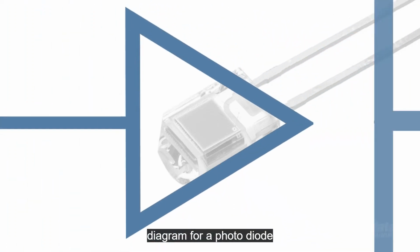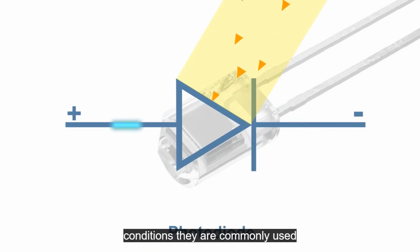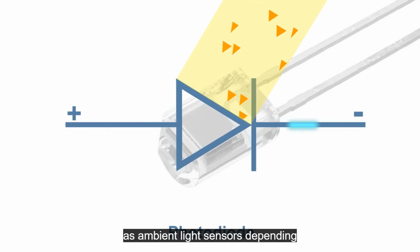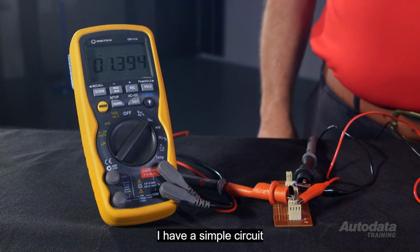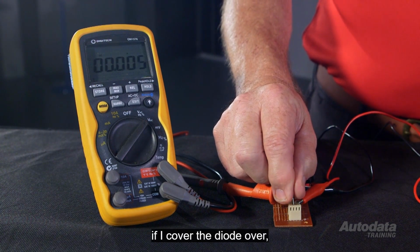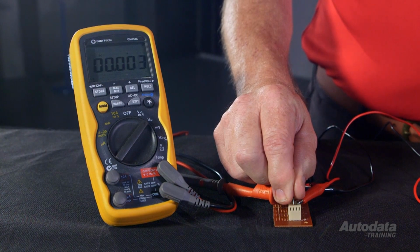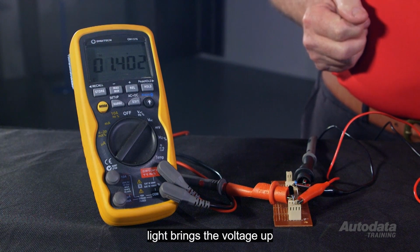This is the circuit diagram for a photodiode. Photodiodes allow current to flow under certain light conditions. They are commonly used as ambient light sensors. Depending on their design and the circuit they are used in, a variation in light levels can be used to suit various applications. Here I have a simple circuit with a photodiode. If I cover the diode over, you can see that the voltage goes down. Exposing the diode to ambient light brings the voltage up.